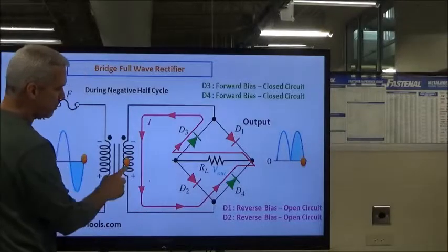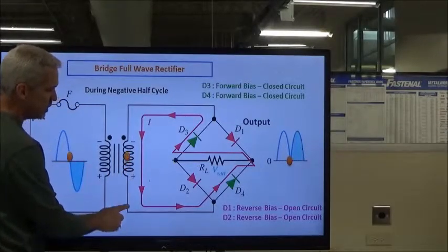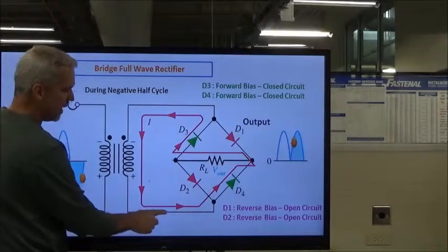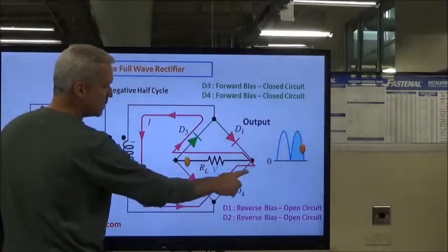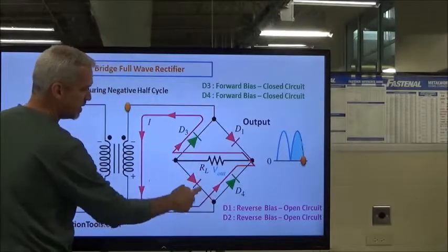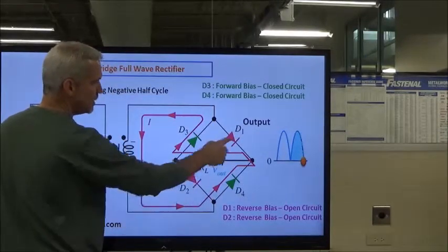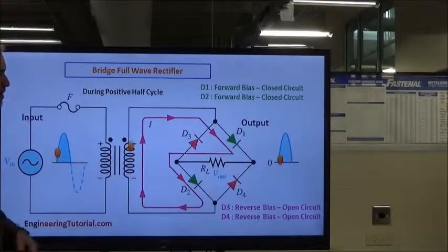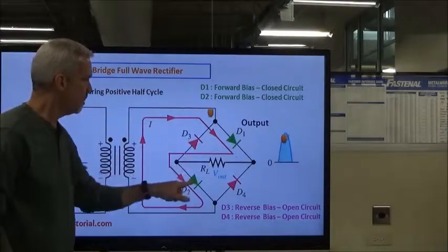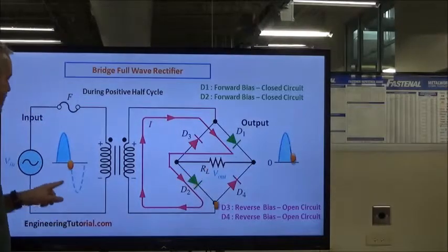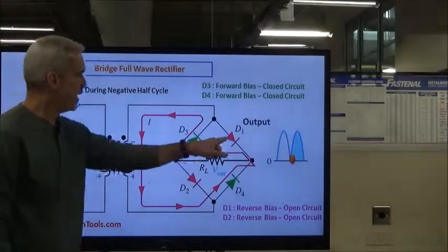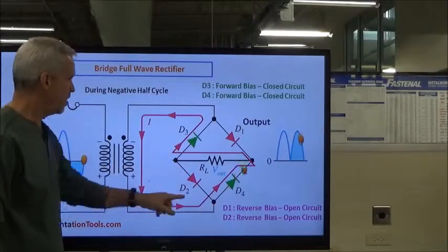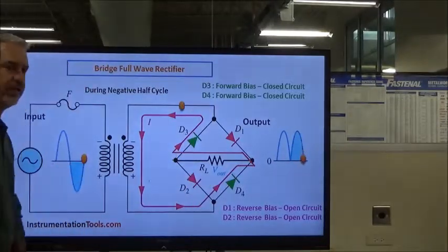Now watch what the little ball does here in terms of the direction it needs to go. Okay, it's coming out of the transformer and going into the rectifier, and notice it's going through this way now. It's being blocked by these D1 and D2. It was being allowed to go through D1 and D2 the first half cycle. Okay, all right. Now the second negative half cycle, it's not being allowed to go through these, and it's now going to come through D4 and D3, okay?